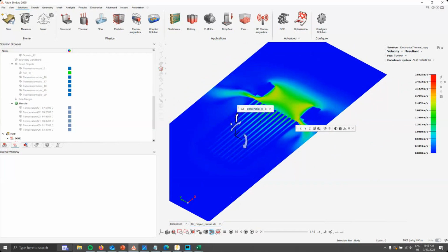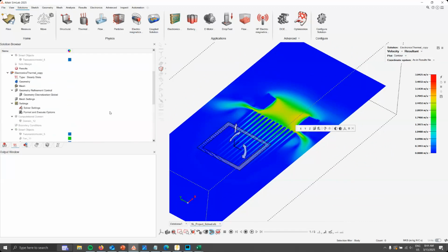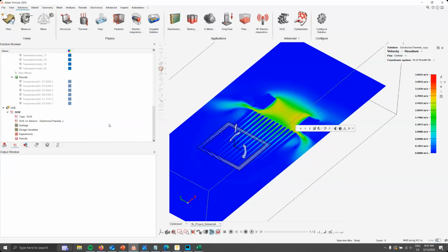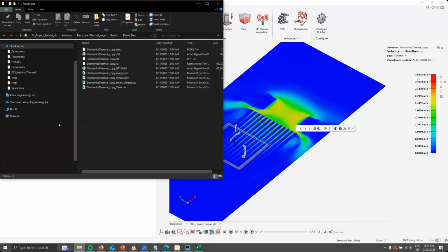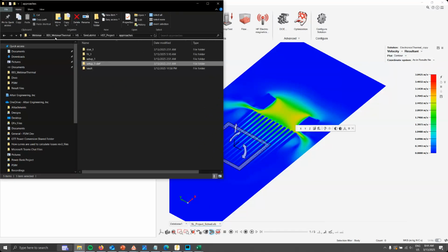And so, as I mentioned previously, the idea from this workflow would be for us to export these losses onto PSIM again, and then keep doing that exchange till we reach a certain point of convergence. Now, SimLab also exports one file for PSIM to interpret. And if we go to results and then the results folder, we can see a parameter file. Let's look for it.